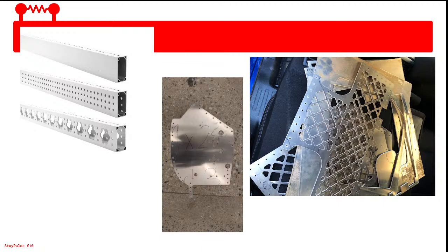What I wanted to point out here, these are from that robot, the one on the cart over there. It's our 2022 robot. This is the shooter plate and the belly pan. Both of these were machined by a water jet. It's aluminum, but the reason we wanted to use aluminum is that we wanted to lower our center of gravity and put a little bit more weight into it. I think that year was the first time we used an aluminum belly plate. Later on, I'll show you examples of what we used to use and why we switched.